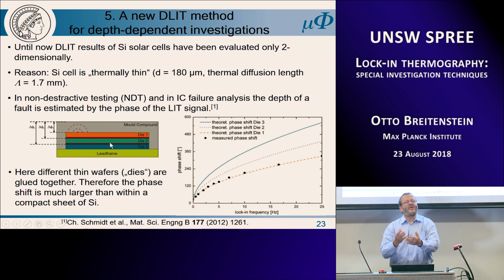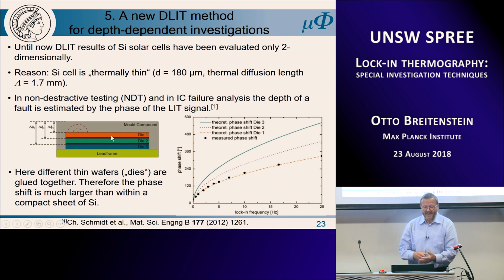For example, storage devices, memories, yes. Often the active layer of an integrated circuit is only a few microns thick, so then they thin it to, let us say, 20 microns per chip, and then they glue several of these chips on top of each other with some glue in between. And in addition, you often have a mold compound where everything is molded together.